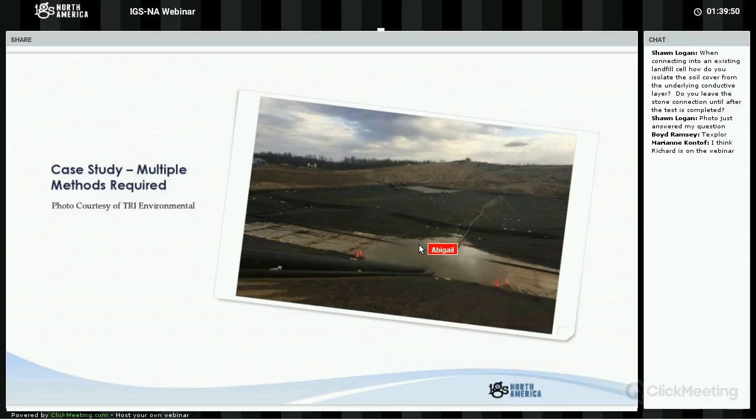And then I came down to the sump and I did the water dipole method. I walked back and forth in the sump. I found one hole using the water dipole method right on the corner. I think it was there. And then I did the soil covered dipole method everywhere that you see covered with mud. In fact, I had them put even more mud on that area to make kind of a homogeneous, muddy area. And we found the biggest hole in the soil covered area right at the edge of the sump, right about there. So we used three different methods.